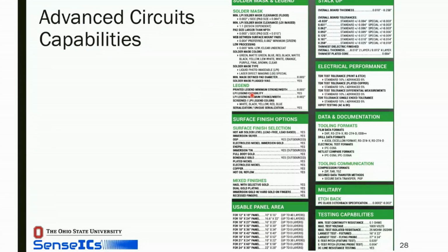Really important, very important section here. Surface finish. Does anybody want to tell me what they think surface finish means? The audience answered that it has something to do with hot air solder leveling. And in fact, if we look at this list, it's probably there. But what the finish is, I mentioned at the beginning, the copper itself will oxidize immediately if you don't have a solder mask over it. But you have to have a solder mask opening in order to make a solder connection. So what do you do? You put something on top of the copper that is conductive that you can solder to. So there are many, many options on what you can use for that.